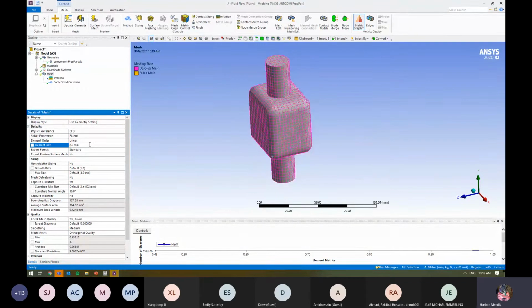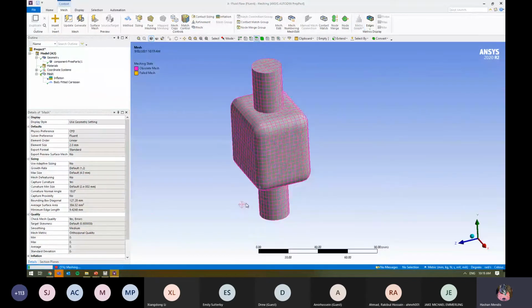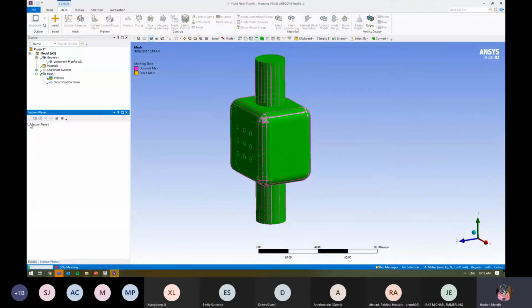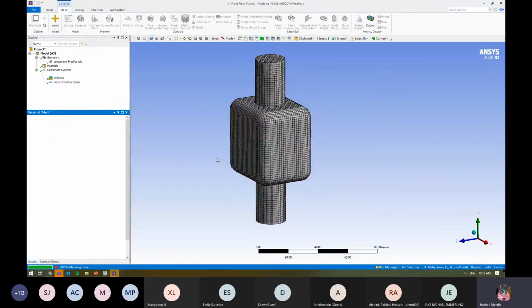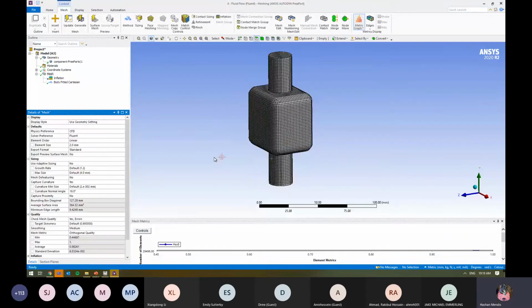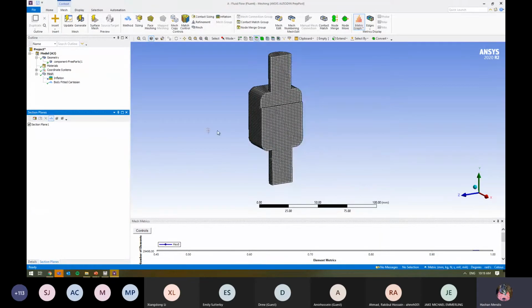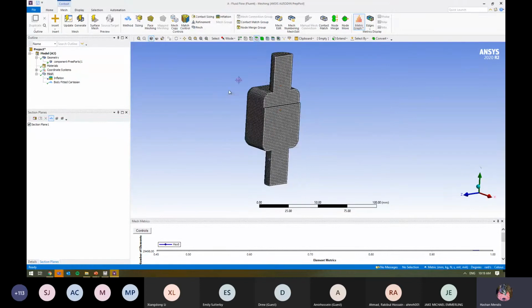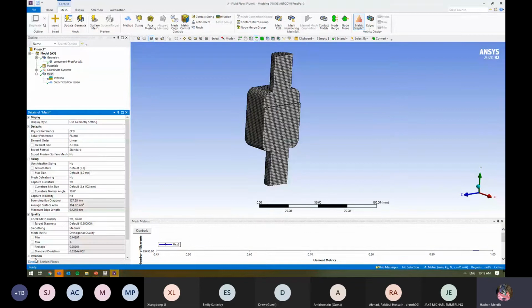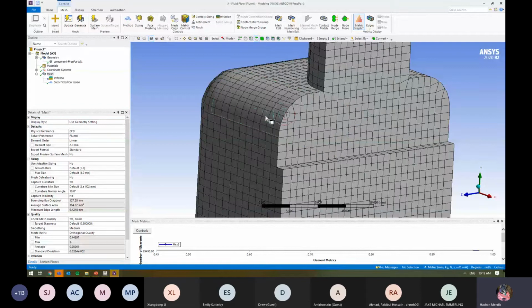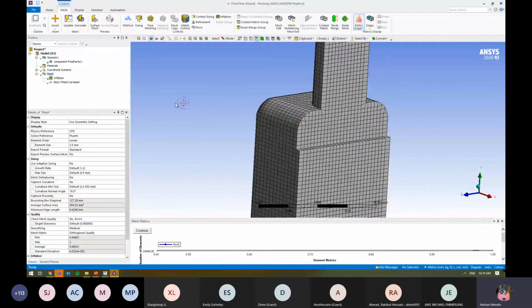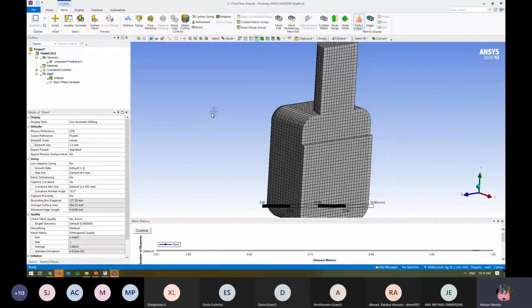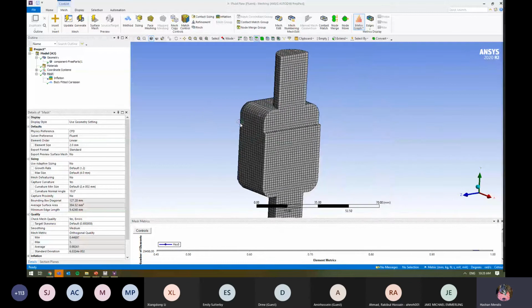And what you can do is then go in there, make the mesh a little bit finer, and generate that grid as well. Right. So depending on exactly what you want to do, you can use these methods here to really refine around some of these regions. Normally, if the geometry is easy enough, it will just stick with hex elements everywhere. But because we've got these complex, curved surfaces, it's going to apply some curvature and it might put some tet elements here and there.